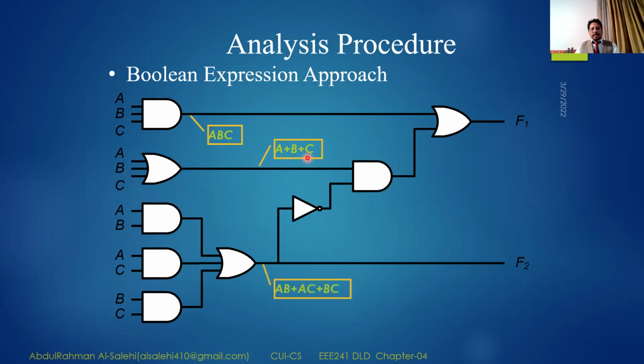Come to the third one here. ORing these functions together, which are the three ANDing gates, what will it be? Sum of these multiplied gates. So it is ORing of the ANDing ones. The first one, the result is AB here as an ANDing gate, plus, because it's an ORed function, plus AC, the second one, plus BC, the third one, it's this one.